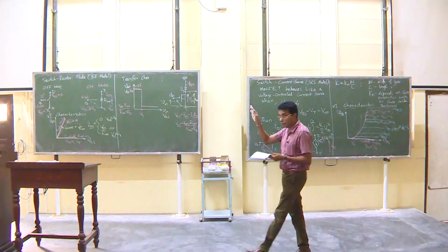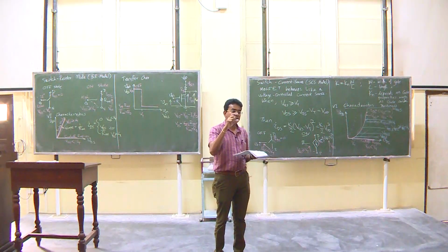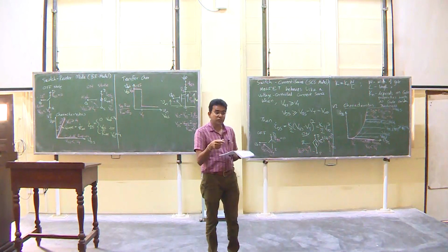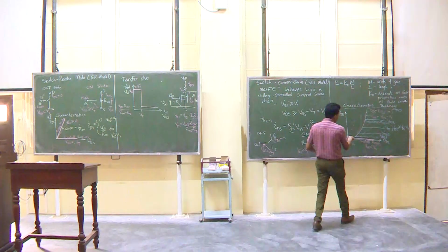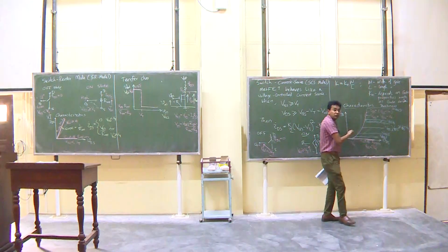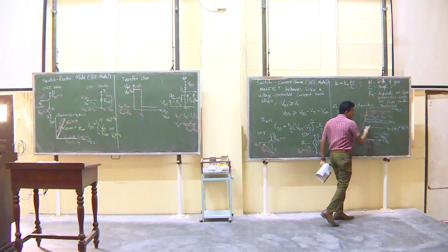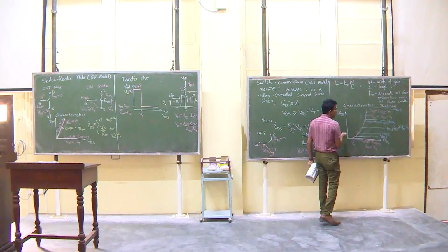Sorry, what I said earlier was not correct. The voltage across it will change according to the circuit, so VDS changes, but the current does not. For a resistor, it doesn't happen like that. That is why it is called saturation. This is constant even when you change the voltage across the transistor output. So this is the saturation region.